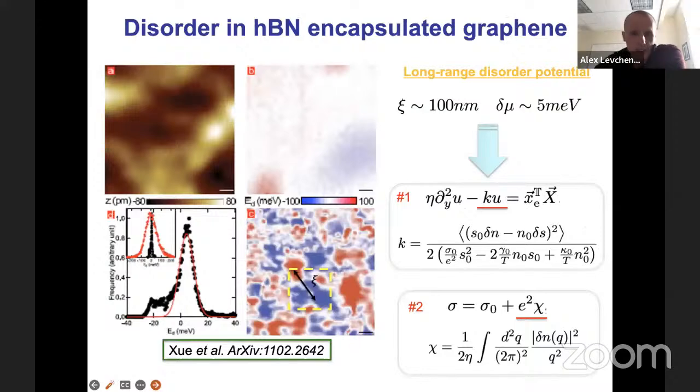So of course, graphene samples are not perfectly clean and homogeneous. STM data shows that the systems, even in boron nitride encapsulated form, are still susceptible to different inhomogeneities, which is called the regime of charge puddles. So up and down sort of lakes of electron-hole-like regimes. They are quantified by an intrinsic length scale, which is experimentally somewhere in the range from 10 to 100 nanometers. This is an intrinsic length scale of long-range disorder.